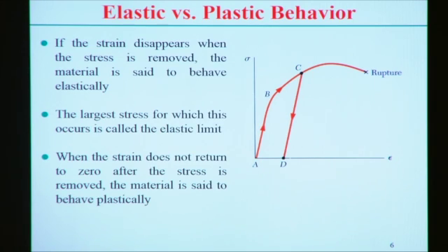Now if there is application of the load in one specific direction, that means uniaxial direction, the figure shows the typical stress strain diagram, where in the initial state from A to B, the curve follows a linear path, but beyond B the diagram becomes non-linear, and up to a certain point it breaks. That point is called the rupture, or the fracture happens at that point.